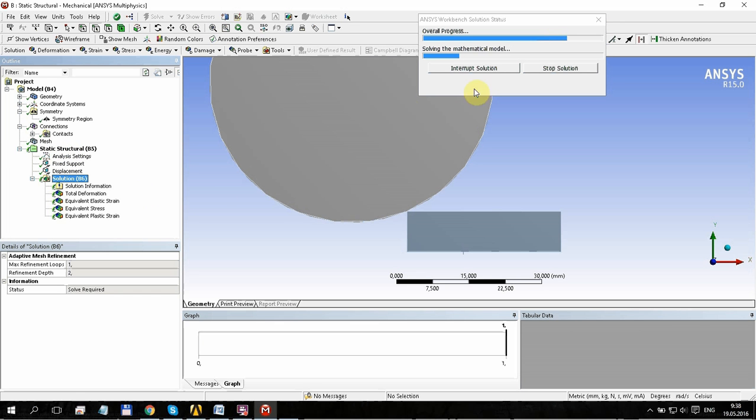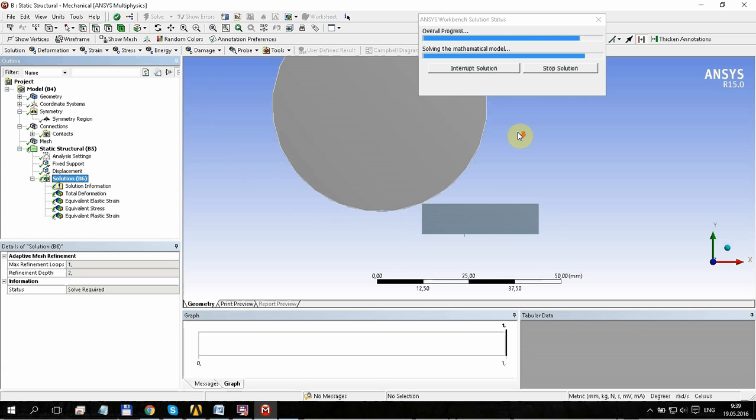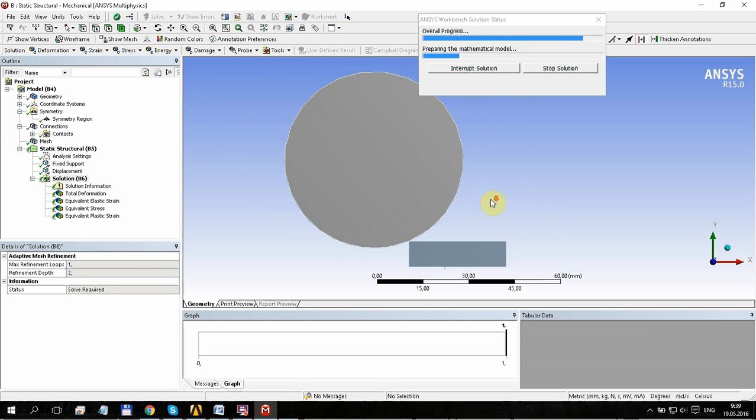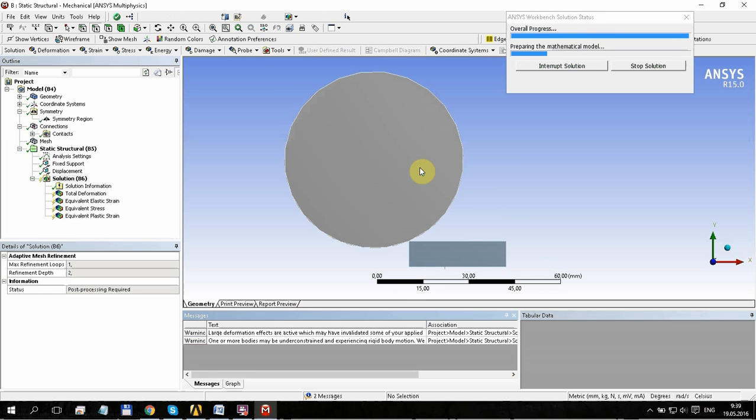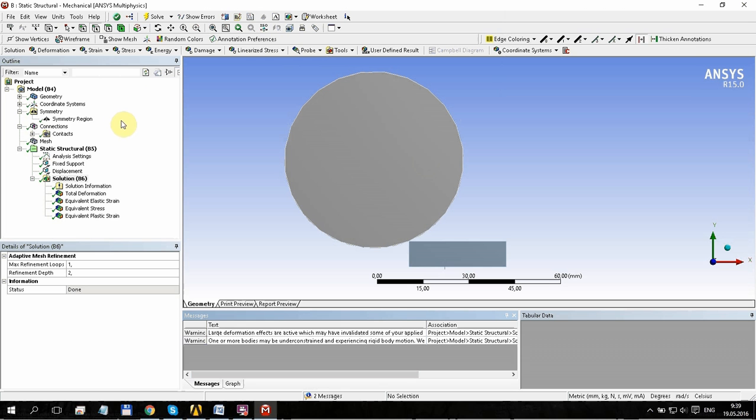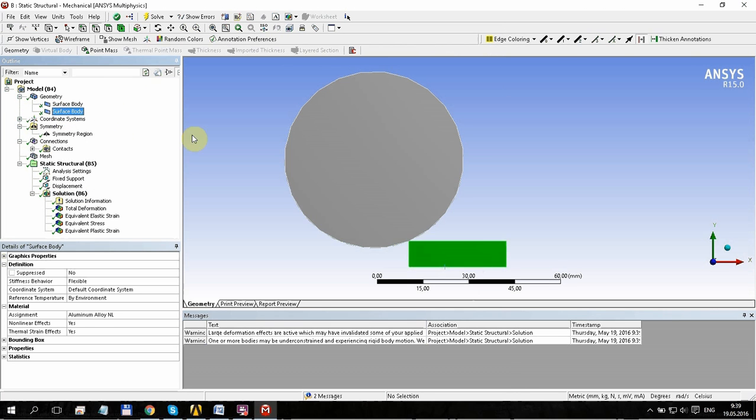Until it's done, I will also add some tips on more complicated opportunities for such simulations. For 3D problems, for more complicated shapes, without symmetry, the steps are the same. You just need to create a roller and specimen, create nonlinear properties for the specimen, and create contacts.